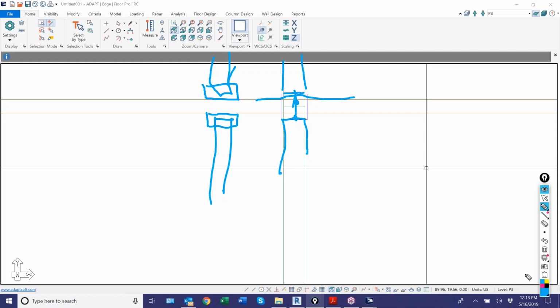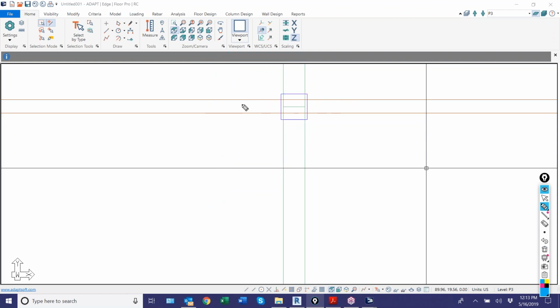So another option would be to model the opening as it was shown in Revit, where the opening actually models to the face of the column. And by doing that, we're going to have an actual slab element inside of that joint that's passing through. So that's another way to maintain the connectivity. You typically will end up getting more elements. You'll get kind of densification of the mesh in that zone at each column, so you'll end up having more shell elements in that case.